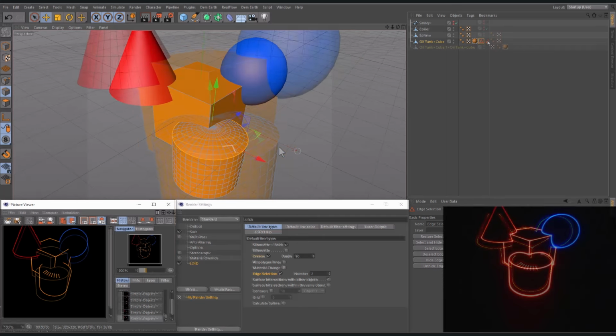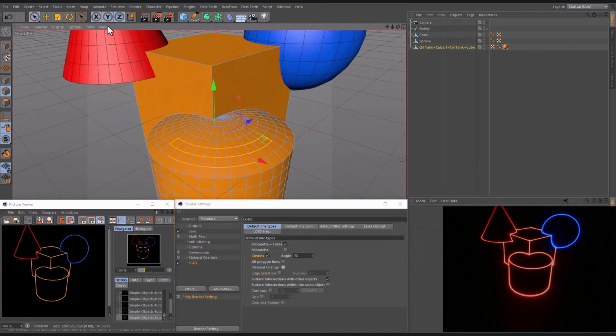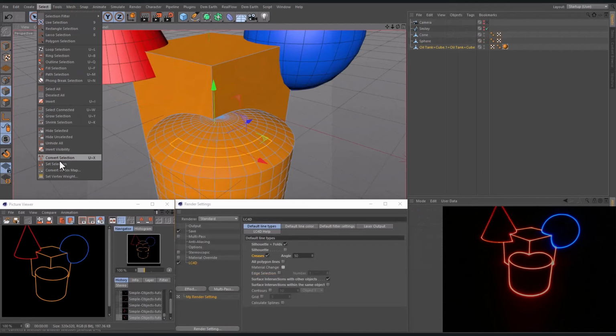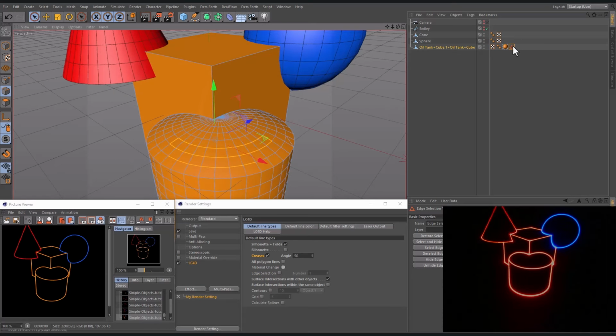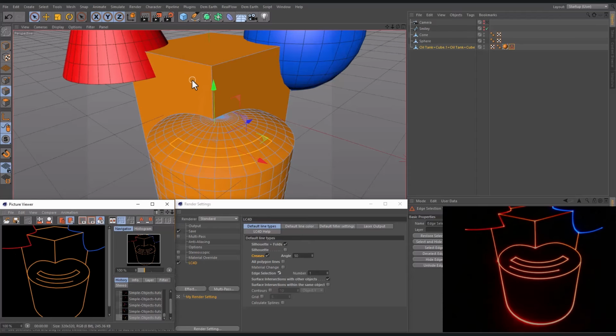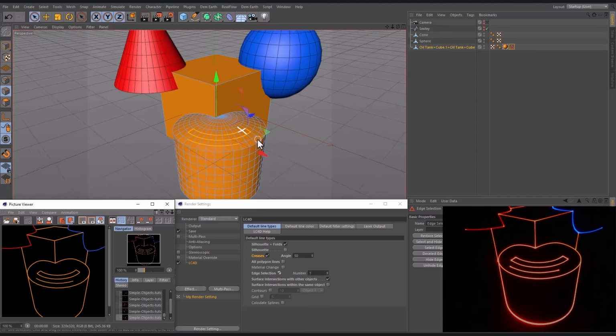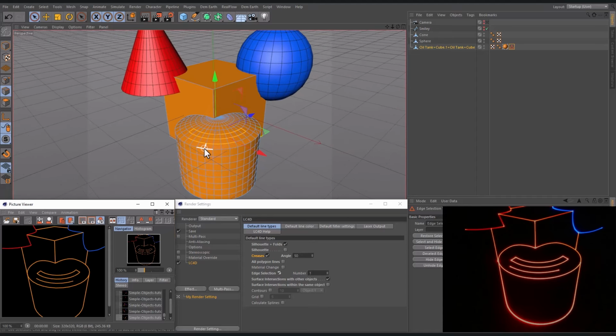And here's another short example of the edge selection tool. I already selected several lines on the object surface. Afterwards, I simply activate the function for edge selection, and in this case I have only one fixed selection. Finally, after rendering, you can see that those previously selected lines are now visible as dedicated rendered lines on the object surface. So, as you have seen, you can use this edge selection tool quite flexibly in several ways.